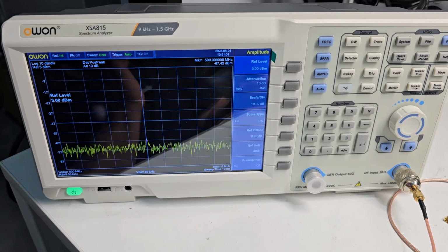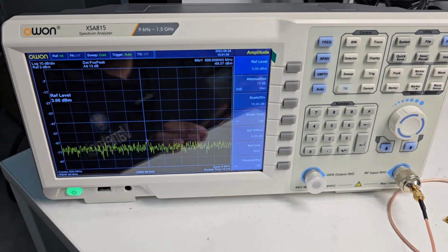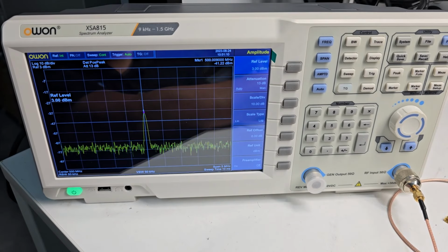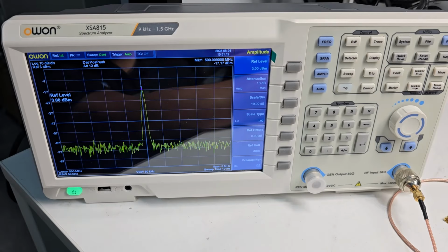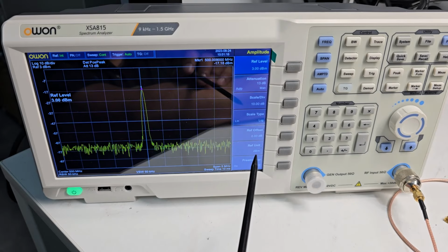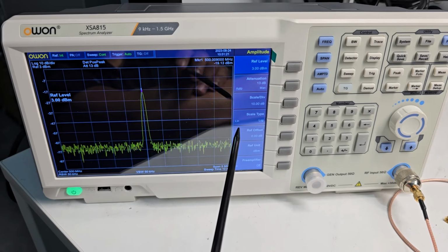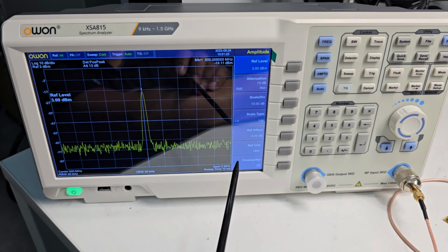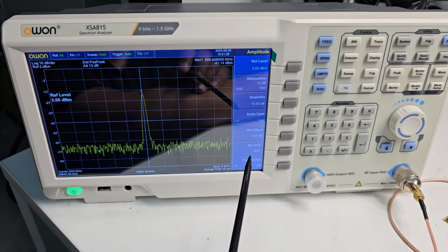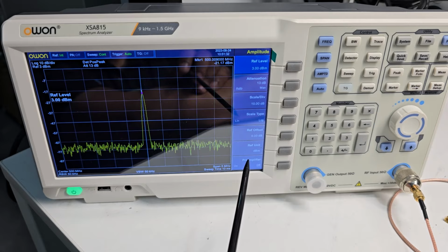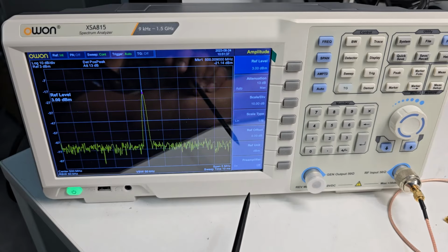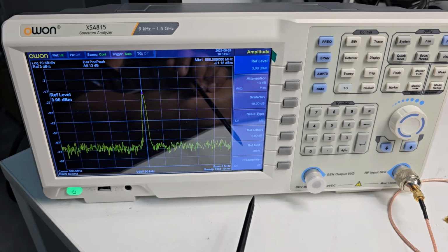Could be the 30 dB attenuator, but we'll find it out, and we are going to go through those steps. So we start with 6 dB. So this is a 6 dB. So our minus 10 minus 6 dB attenuation, we have a minus 17. So we'll keep increasing to 8 dB, 10 dB. So the 10 dB is minus 21, where our drive level is minus 10. So it roughly drops by 10 dB.